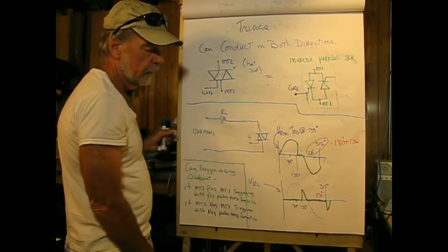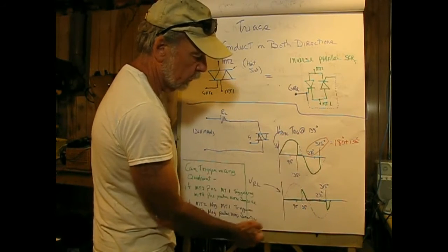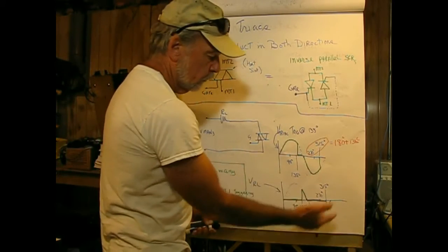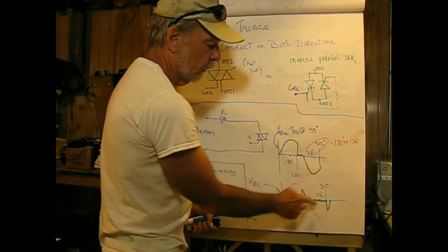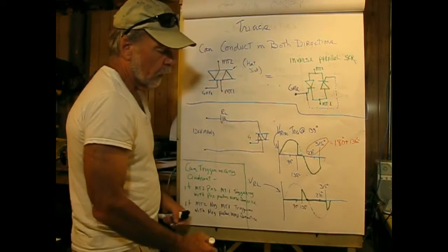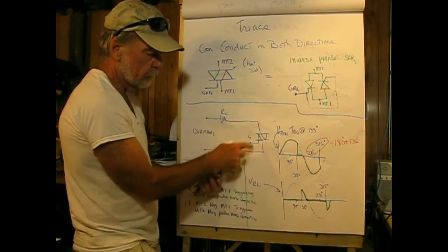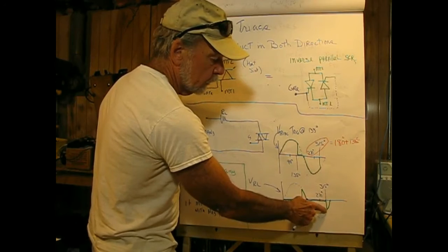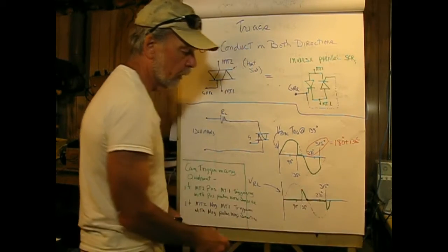0 volt value. Likewise, on the second half cycle, we're triggering at 135 degrees, and that translates to, if we're talking about a complete cycle, 315 degrees, and that's really 180 plus 135, relative to this point right here. So when the input waveform goes through 0, again, the holding current minimum is met, the triac turns itself off and stays off, so this voltage would be across the triac until it triggers, drops to 0, and then the rest of the voltage would be across the load, which would follow out the rest of the sine wave.